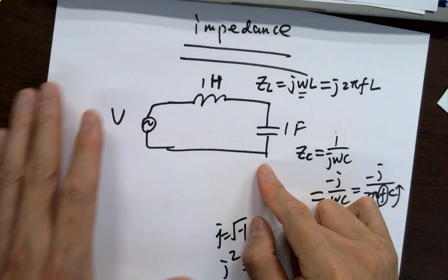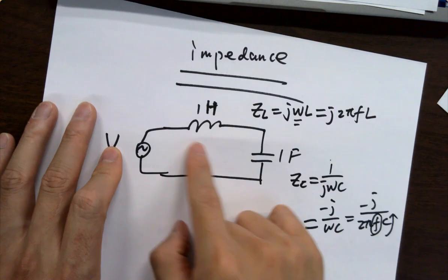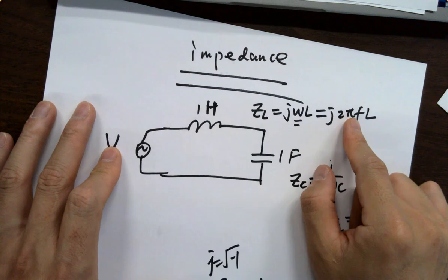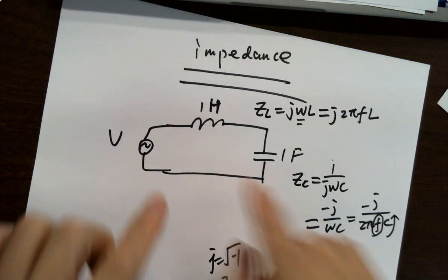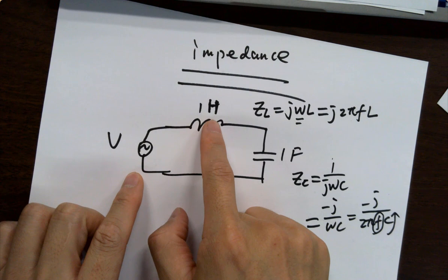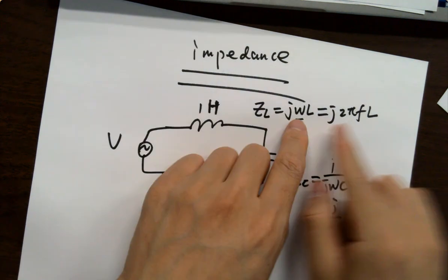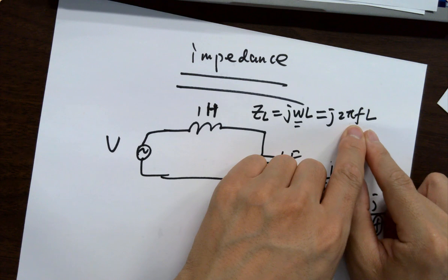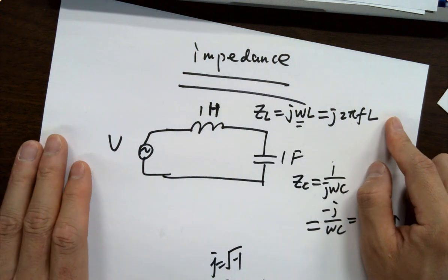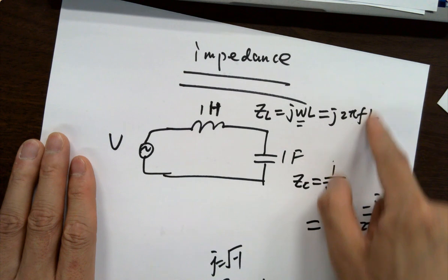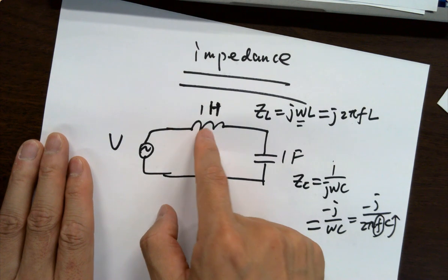So AC comes through. For an inductor, like what I said, if you put an inductor in the circuit for 100 years, what's happening? The inductor becomes a wire, right? So for the DC signal, the inductor is a wire. Why? Because the frequency is 0. For an AC signal, if the frequency goes up, the impedance goes up. So this actually blocks the AC signal.